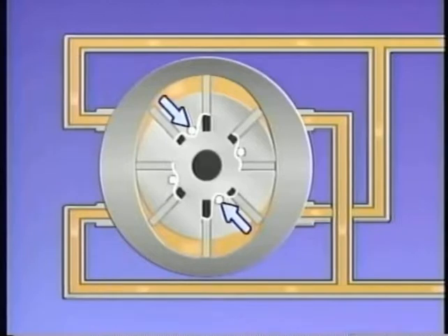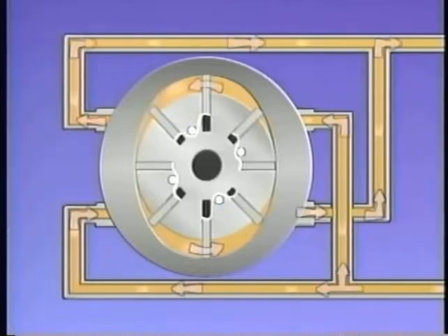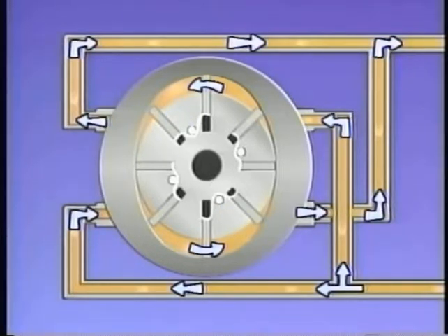Generally, springs are used in hydraulic motors to keep the vanes extended against the cylinder wall during operation. The fluid flow to a hydraulic motor can be reversed to cause the rotor to turn in the opposite direction. This makes it possible to reverse the turning direction of the device connected to the drive shaft. In a hydraulic motor, just as in a double-acting piston actuator, flow can be reversed with the use of a directional control valve. Now, that's basically how a hydraulic motor produces rotary motion.